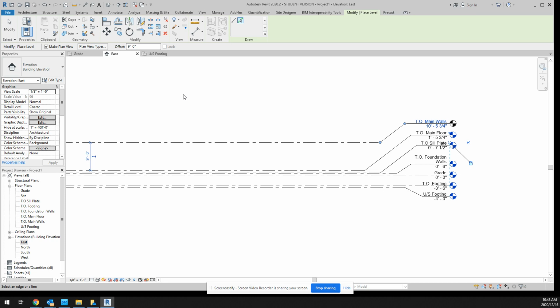Okay. If you want to get creative on the outside of the building, so say you want the first 3 feet all the way around your cottage to have stone on it, and then you'd have siding above it, what you would then do is create a level for a stone accent around the perimeter of your building that's 3 feet high, which is called a stone skirt. So you'd create a level that says top of stone skirt, and you'd set it at 3 feet, 4 feet, however high you want it to be.